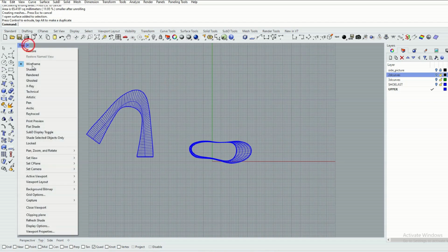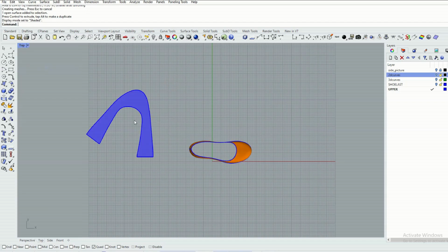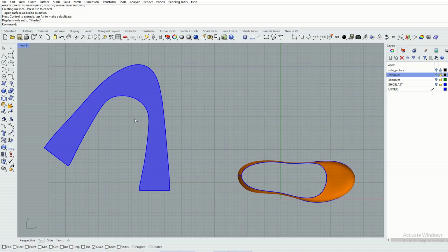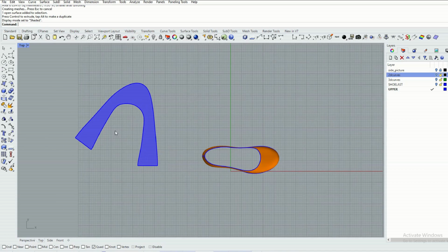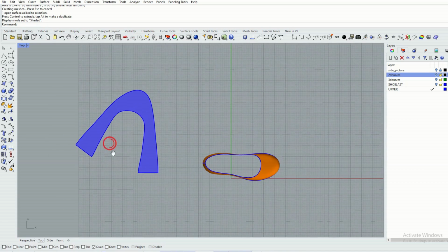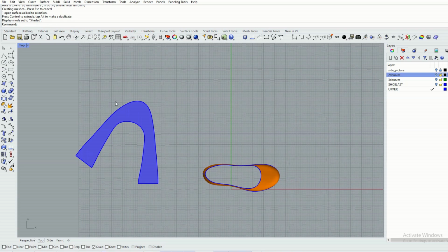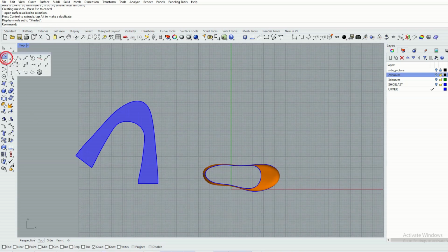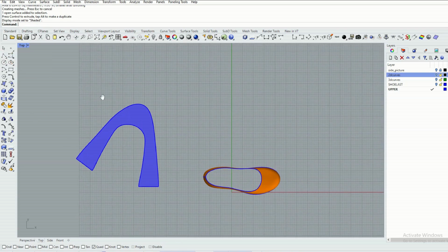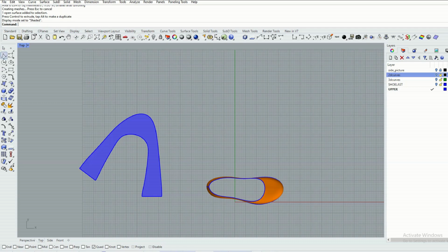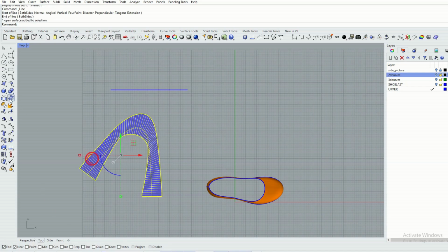You can then orient the object and trace the various curves. Let's do an operation that simulates this step very quickly. So I'll take the line command, draw a horizontal line, activate the end snap and the near snap, and select the surface.